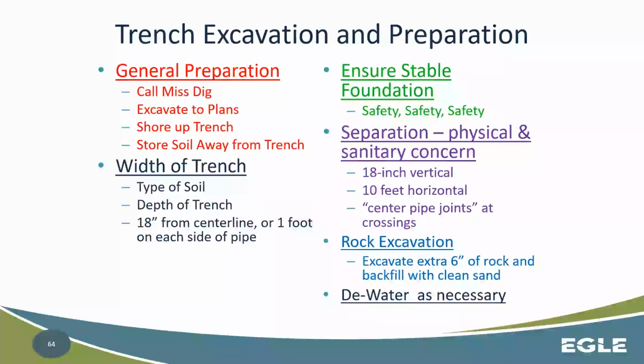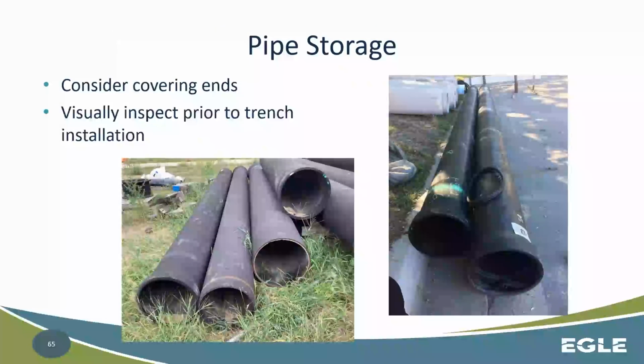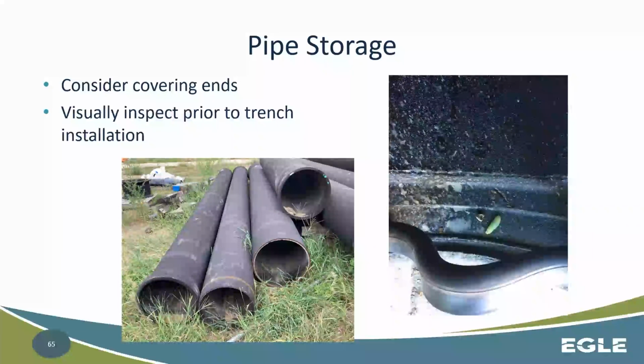Okay. Rock excavate an extra 6 inches of rock and backfill with clean sand. Okay, making sure that foundation is solid, and then dewater as necessary. Okay, so pipe storage, make sure the ends are covered. Make sure that they're cleaned, and there's not too much debris getting in there. As you can see from these, they're probably pretty inadequately stored opportunities for water mains here.